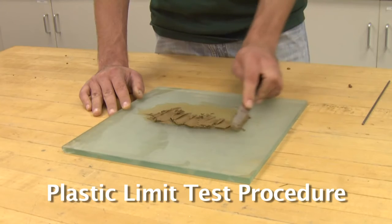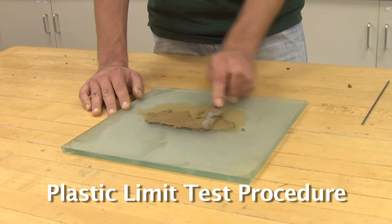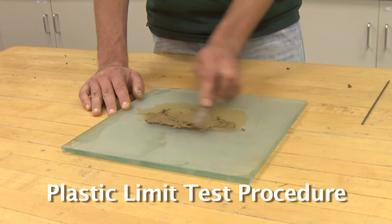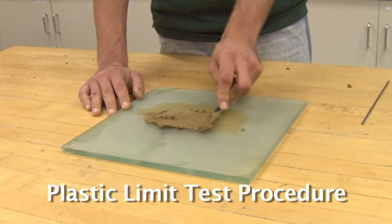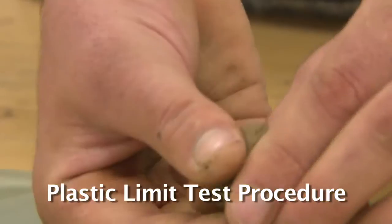The plastic limit is the average of the moisture content when the soil starts to crumble when it is being rolled into a 3 millimeter thread. So you take a 25 to 30 gram sample, spread it on the plate to dry it out. When it gets to a workable state, you can pick it up and start working it in your hand.